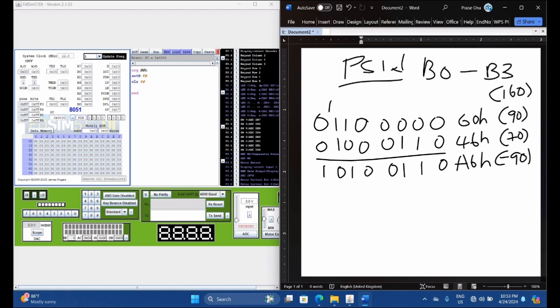Because this is a signed number, because you're having a 1 as the most significant bit, it's going to give you a negative. So you'll be having a negative answer. But meanwhile, these are positive decimal numbers, and adding positive decimal numbers, they shouldn't give a negative answer. In such cases, it simply means that there is an overflow. In layman's terms, you can say there is an error somewhere. So that's how the overflow tends to happen.